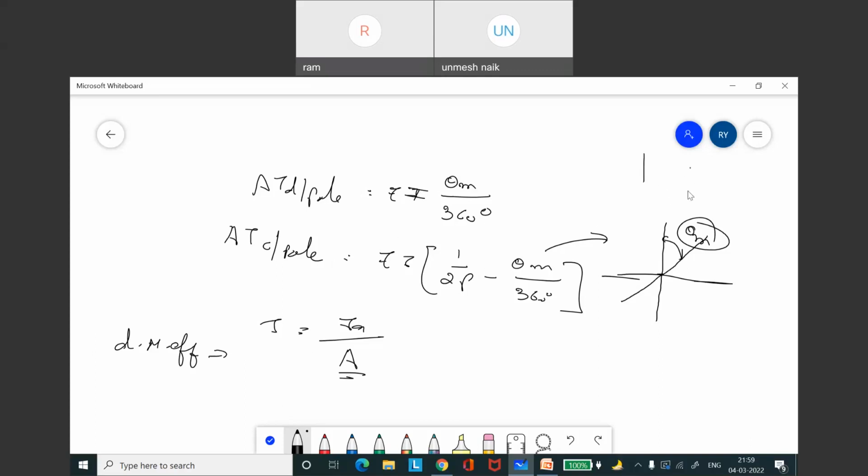See, here we have the pole, and this is our armature. Here they will have some drill holes, and in these they will place conductors. These conductors are called the compensating winding, and they are connected in series with the armature.